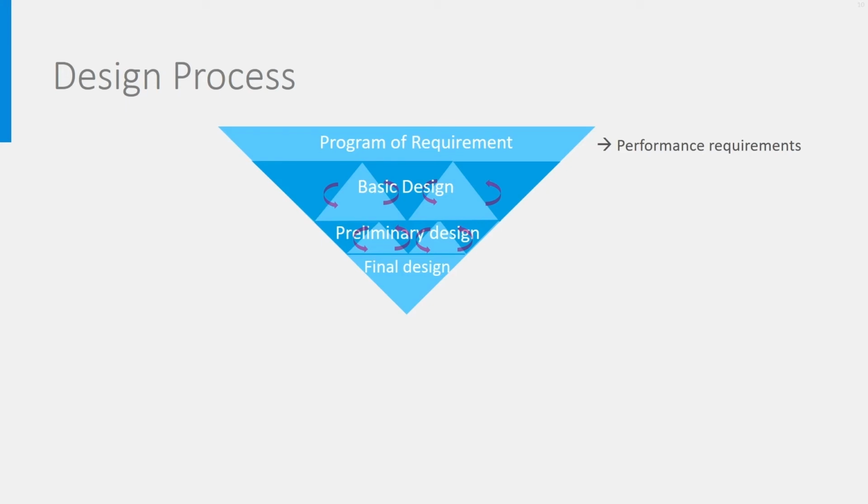Will the direction be more towards heat pumps or connection to district heating? Is it going to be a high-tech HVAC with lots of controls, or a less sophisticated but more robust one? Which insulation level will be chosen? What type of glazing is recommended? Which zones can we think of? Will the ducts be sized for all air or for hygienic air? What about solar panels, etc.? This phase is creative and interactive.